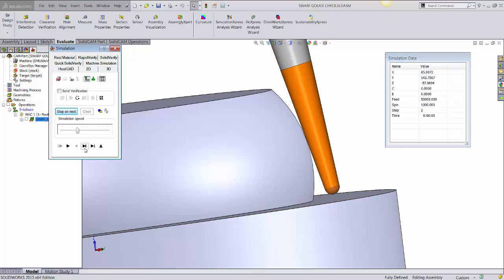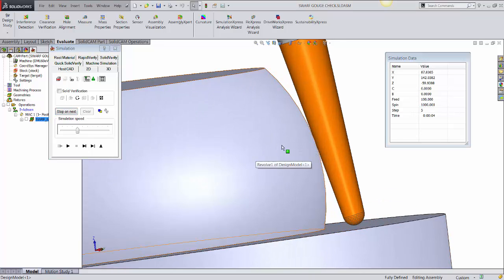So let's look at our first entry. You can see that the tool has been pushed out of the surface till it's no longer gouging this particular curved surface. This is the first option which is used to degouge the swarf surface. However, we have an issue here, that is a lot of material is being left out. Now many times it happens that this particular surface is not much of a relevance. What is more relevant is how you are getting the surface with minimum material being left out. Gouge is allowed, but not a lot of material needs to be left out.